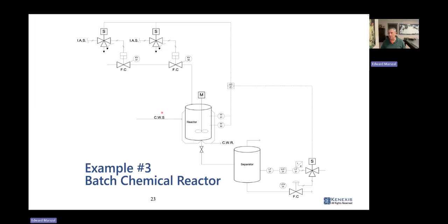So why are we doing this? Well, in this particular case, if you're going to stop the reaction, we don't want the level to continue to drain out of the system into the storage tank, because ultimately you're going to be sending vapor out to the storage tank. You might cause an environmental exceedance. And at the end of the day, when we restart the reactor, we simply want a level to be in here. So it's going to ease our startup.